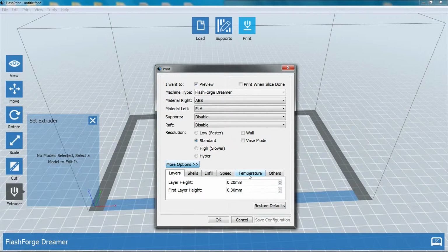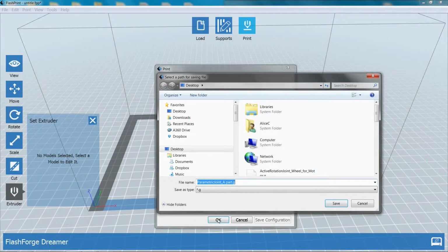For PLA, the recommended extruder temperature is 205 degrees and platform temperature is 50 degrees. The infill indicates the density of the filling structure of the part. 15% is good. For the other parameters, default values are usually okay.